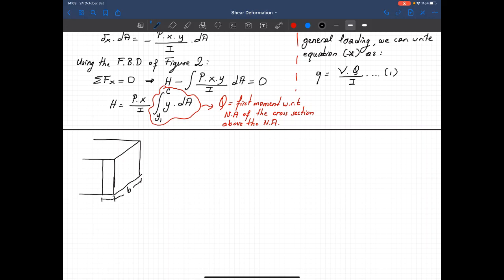Okay, and this distance is delta x. And the way we will see the shear force distribution, the horizontal shear distribution, is as follows. That's what we see. Okay, when you write everything in 3 dimensions, I should have this same shear distribution in this face. So what I did here is, remember, we always show the shear as follows, right? That's the shear force. So I drew this shear diagram in 3 dimensions.